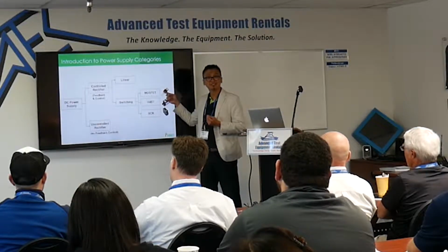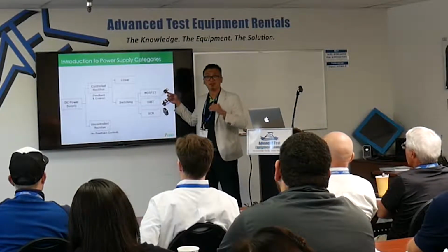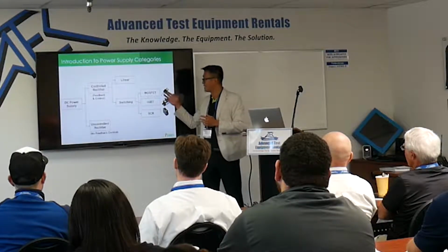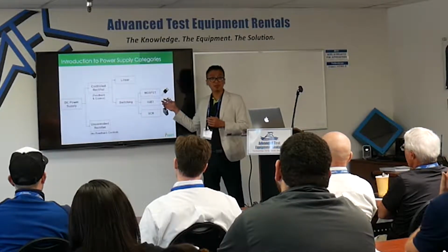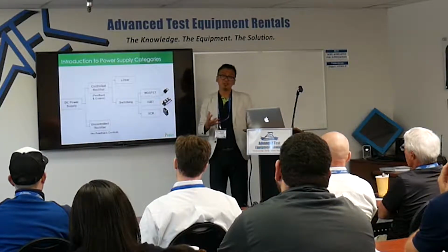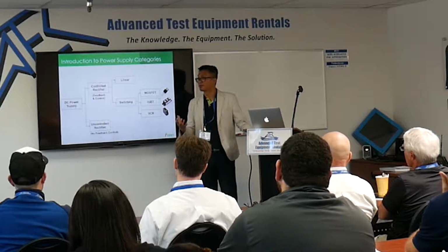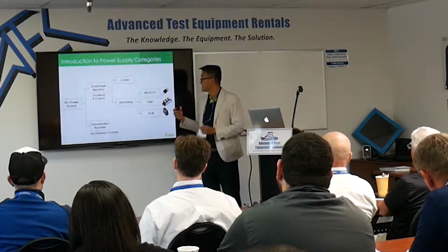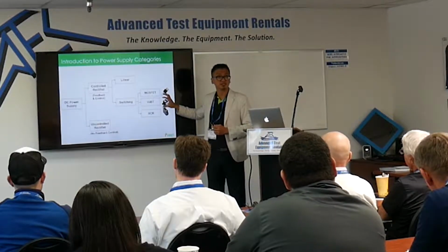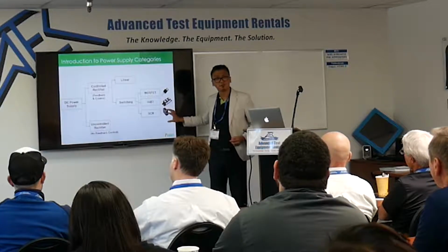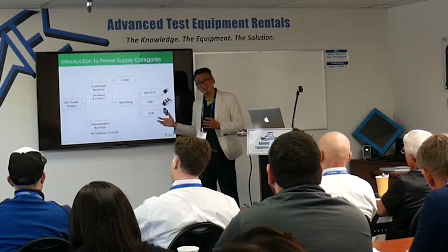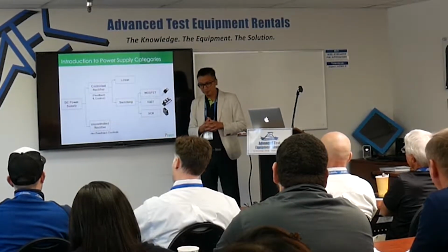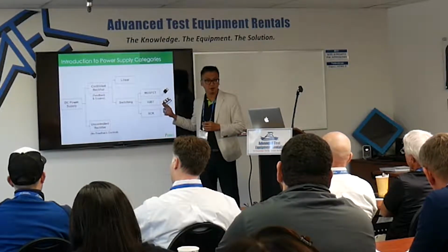Anyone think MOSFET? Why is it not? Anyone think IGBT? Okay, cool. So typically, MOSFET is faster than IGBT. But nowadays, a lot of IGBT manufacturers, like Infineon, are making very fast response IGBTs as well. But typically, MOSFET is still faster than IGBT. Okay, and SCR type, the response time is slower, but SCR is a different technology, more like a transformer and SCR in there. So the response time is relatively very slow.